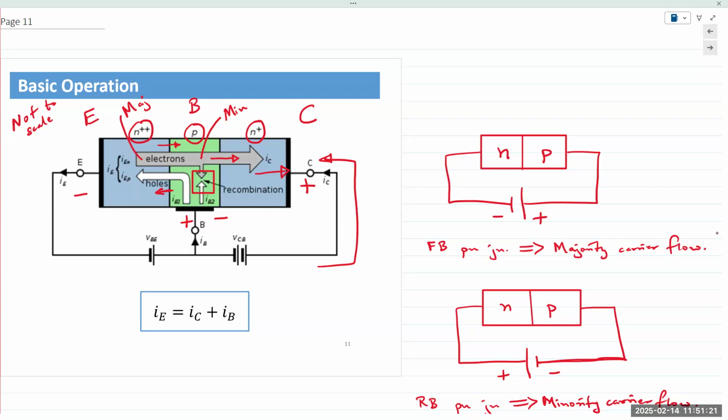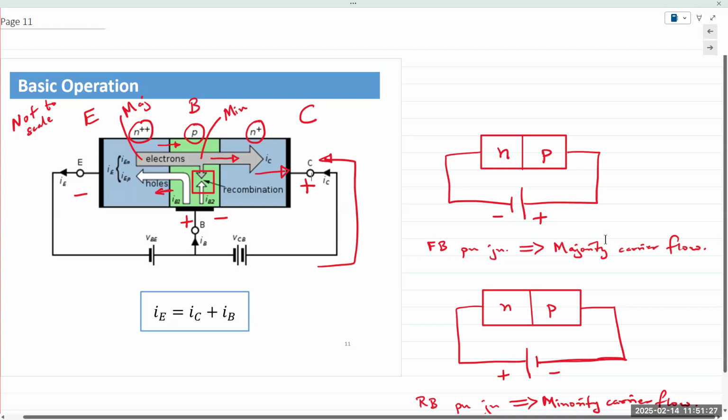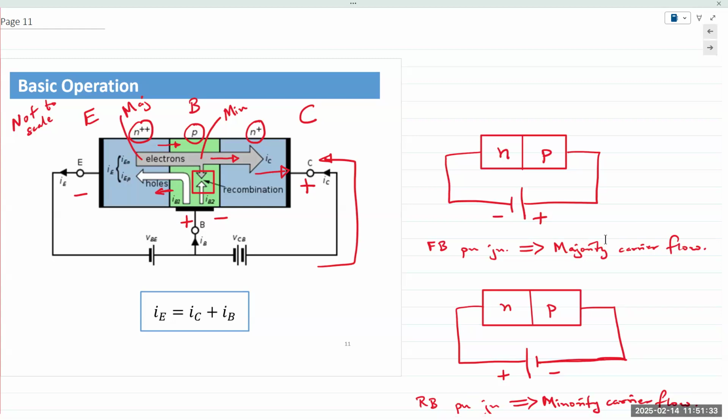But the current wouldn't go negative in that case, would it? Sorry, what was the comment? You were saying that if you apply an AC signal to the valve or the base in this case, that the DC would become an AC waveform. Well, it's just a simplistic way of stating things. But when the AC signal goes negative, then the base would be in reverse bias, so then there would be no current flowing, right?